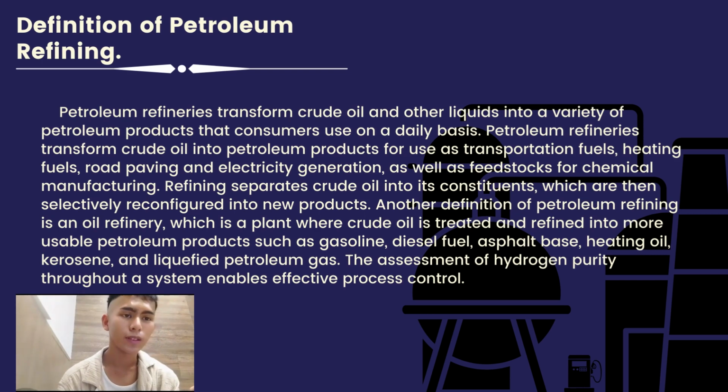We move to the next step, which is step 6, fuel gas specific gravity. What is the meaning of this? The process headers and on-site power boilers are heated with the fuel gas and some extra hydrogen as the burner fuel. And the burner rate is determined using the fuel gas specific gravity.